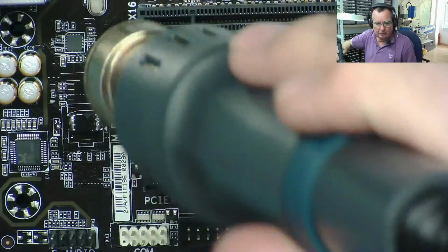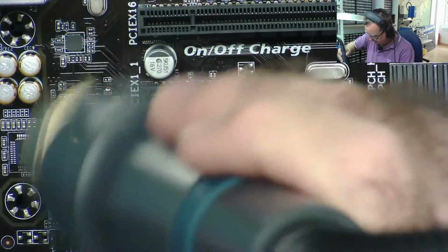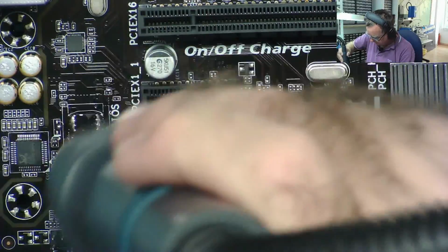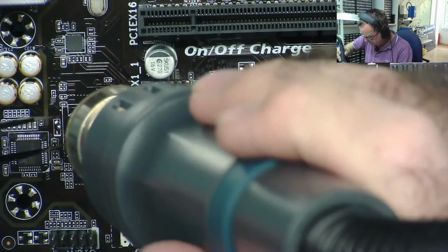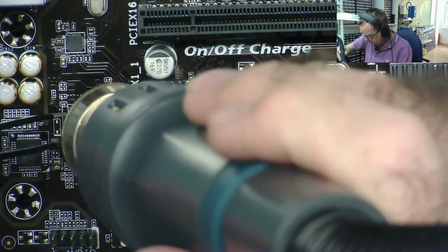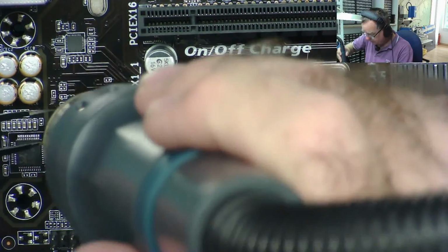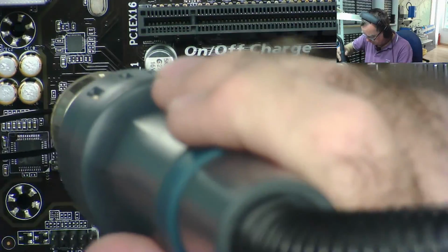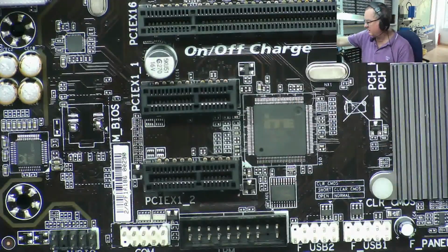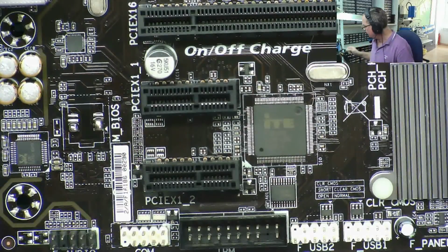450 and full blast. And this will melt now before anything around it melts, so you haven't got to worry about nearby components. This is going to melt first. Get heat in towards it. It'll come off quite shortly. Yeah, like that. Just be careful if you do it this way that you don't get a blob of solder landing back on the board, because you put a lot of solder.